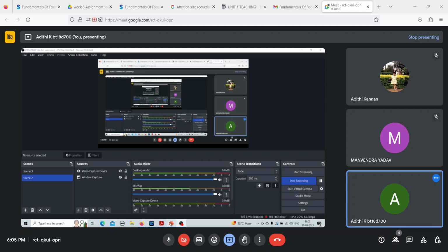Upon further simplifying and carrying out the integration, you get x bar minus 1 divided by minus 1 on integrating the RHS. On simplification and applying the limits, you get E is equal to Kr, which is Rittinger's constant, into 1 by xp minus 1 by xf, where xp is the dimension of the product particle and xf is the dimension of the feed particle.